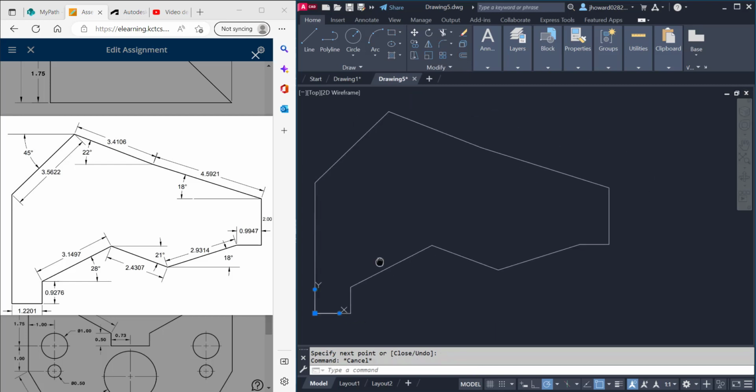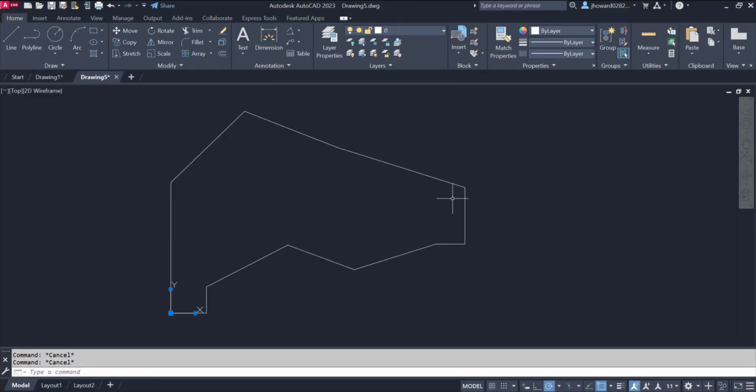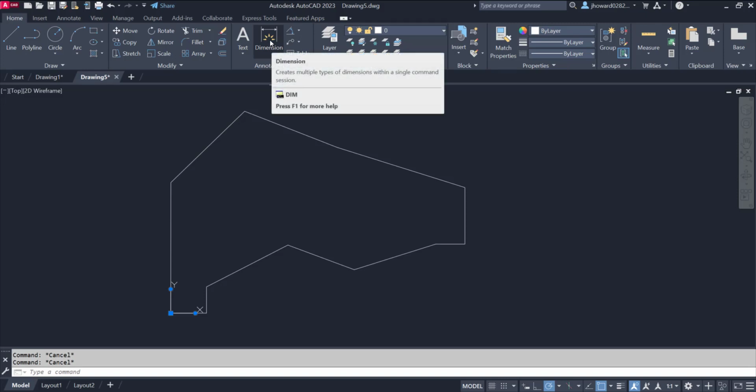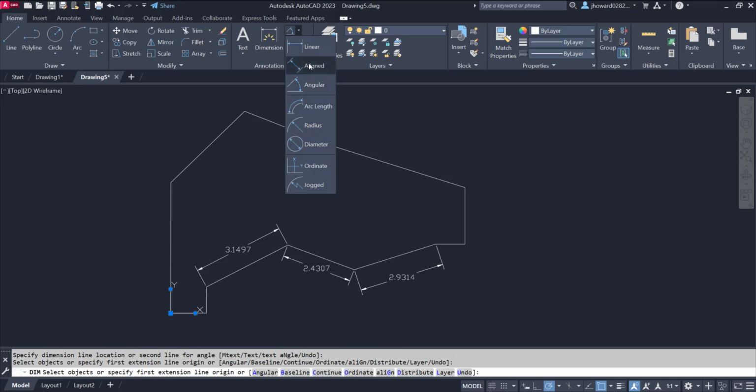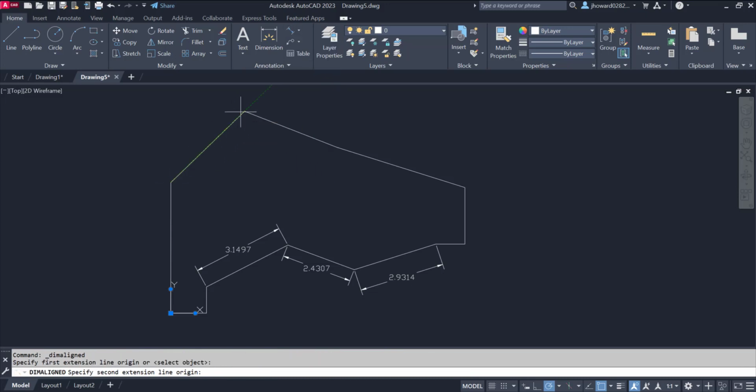All right, so I want to show you real quick too, guys, how to annotate this. I kind of showed you already with the angle there, but here's this dimension, little smart dimension. You can go here and click it, and y'all see how it measures it for you. You can also hit this little button here and do a line. These are aligned measurements when you follow a measurement, because if you go in here and just do a regular linear dimension, it does it in horizontal and vertical.